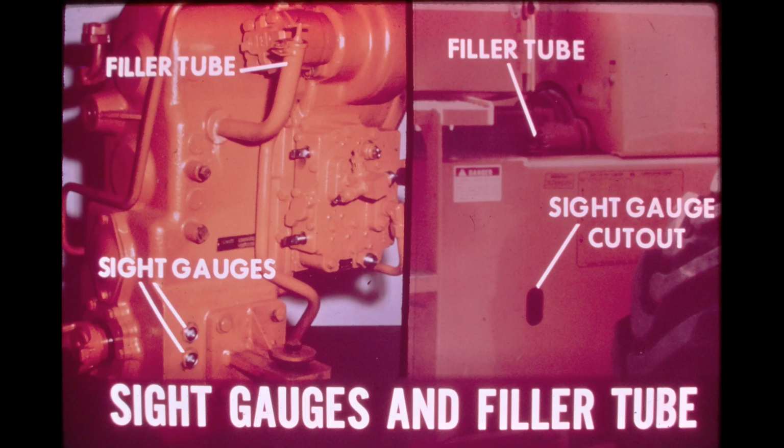If the oil shows signs of aeration, a suction leak or inefficient pump could be indicated. If the oil needs to be changed, both the pressure filter and the suction screen should be serviced. Contaminants found embedded in the filter elements can be helpful in determining the location of the failure. For instance, aluminum particles would indicate converter component wear. Steel particles could indicate pump or control valve failure.